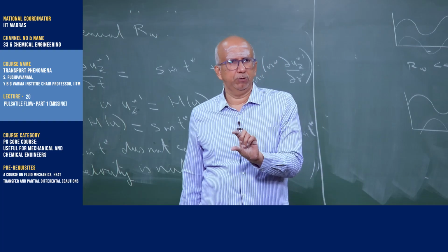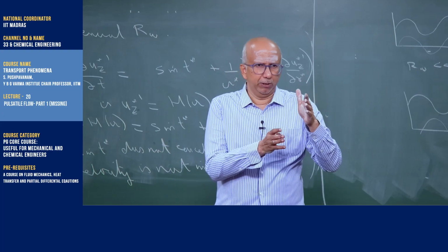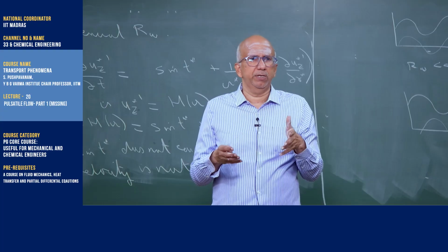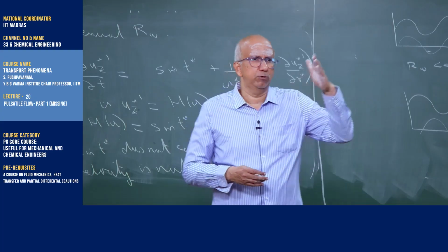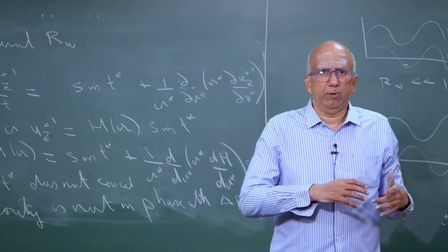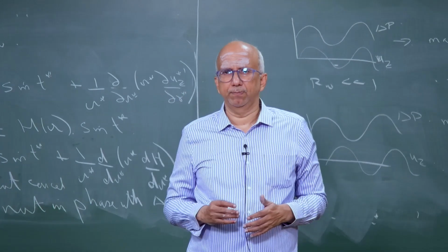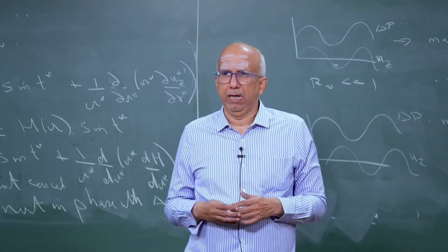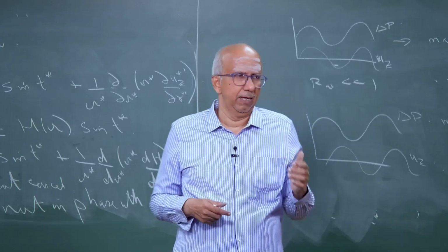So I have delta P1, I have delta P2, next time instant the liquid quickly adjusts to the new pressure drop. Again you change it, liquid quickly adjusts because the frequency is very, very small. If the frequency is very fast, the liquid will not be able to adjust and there will be a phase lag, and that is what you are seeing.